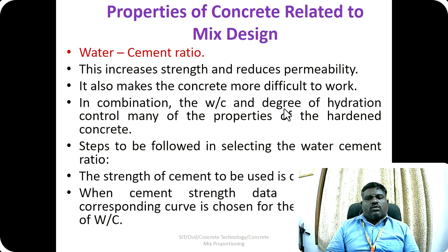So the hydration of the concrete mainly depends upon the amount of water we added, right? Similarly, the strength of the concrete is also decided by the amount of water we added during the mixing. So we have to use the required water cement ratio for achieving good concrete.